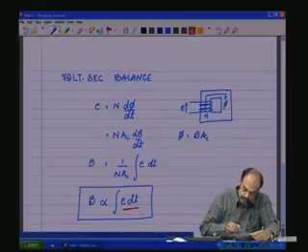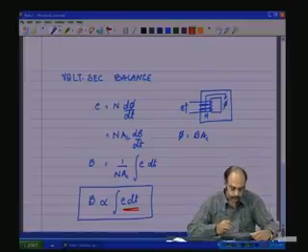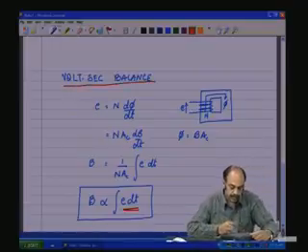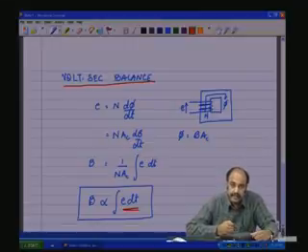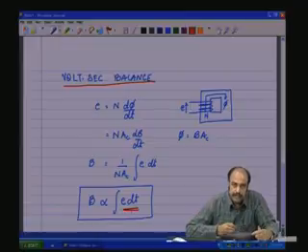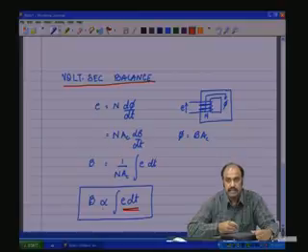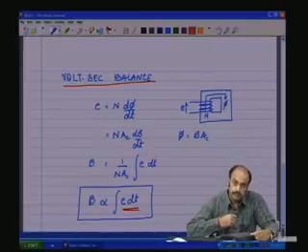This is the volts and this is the second. That is what is known as the volt second balance, meaning this integrand on integration should not have a waveform that is continually increasing, meaning E should not be a DC value.